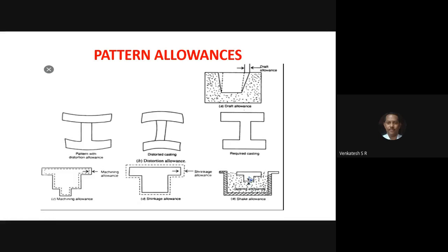That is called shake allowance. You cannot remove the pattern in a straight upward direction as it is. You require a little shaking operation to remove the pattern from the sand.